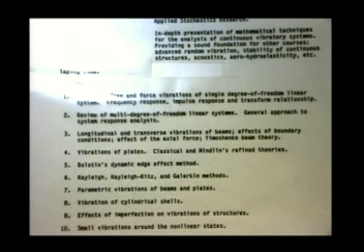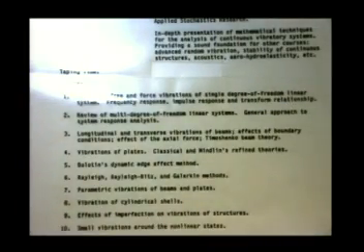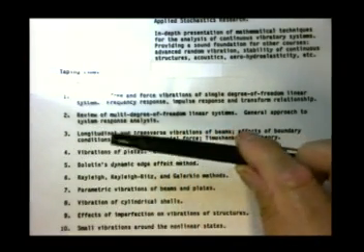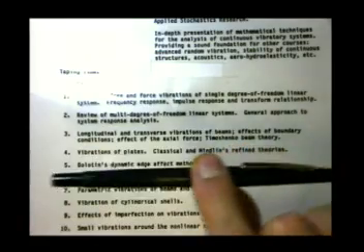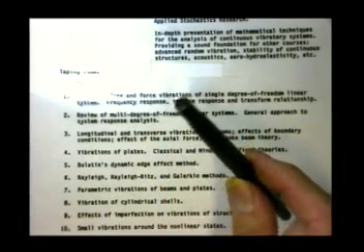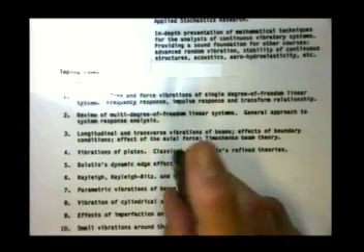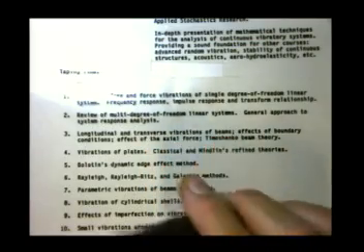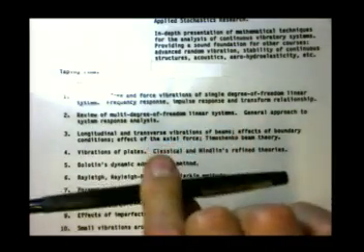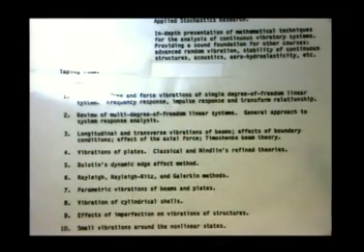Plates are two-dimensional objects, like this paper that I'm showing to you, because it has 2 dimensions that are commensurable with each other. These 2 dimensions are of the same order of magnitude. In a beam, one of the dimensions, the length, is much greater than the 2 other dimensions, which are in the cross-sectional area. So this is what a beam or bar is. Plates.